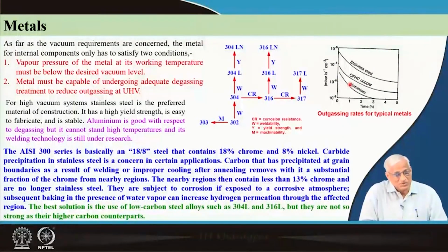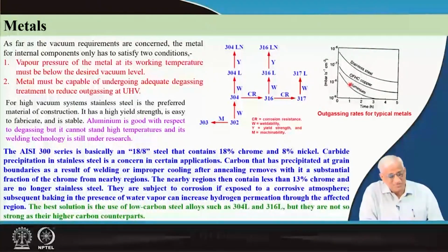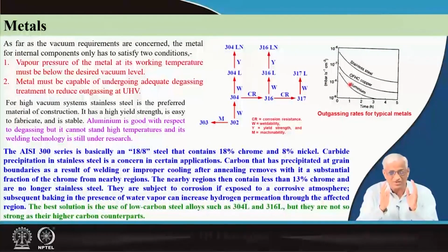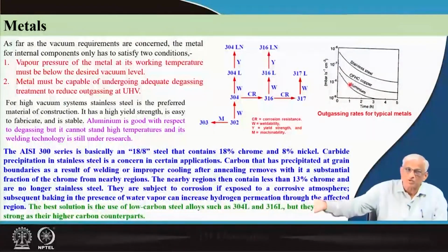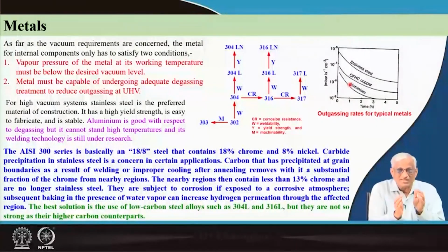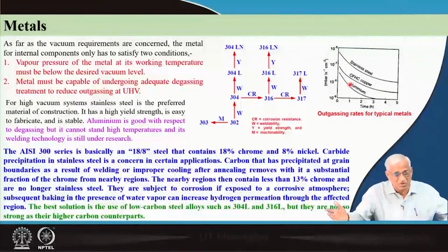So welding is not possible, and aluminum cannot stand high temperatures, but it is ideal for manipulated materials inside the vacuum chamber. Different materials have different roles to play. Copper is very good for feedthrough materials, where you can pass high current from outside to the inside. There are applications for every material in vacuum, some in small quantity, some in big quantity.